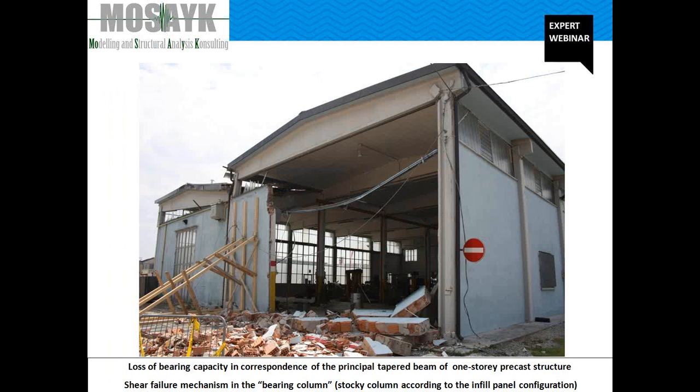Another frequently observed failure typology is, as we have seen before, collapse of cladding panels consisting both of brick or light brick masonry and precast reinforced concrete element. Concerning the former, traditionally used in buildings, let's say, of category A, incipient collapse was observed to be associated mainly with high out-of-plane slenderness because no lateral restraint was provided in correspondence with columns and reinforced concrete spandrels.